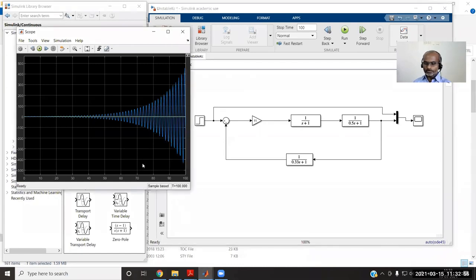Okay, have you understood so far? To quickly summarize, say we have a closed loop system. The closed loop is coming because of a measurement and controller combination. And with P controller, there is always an offset in the system. With I control action, we can eliminate the offset, but it is going to increase the order of the system.